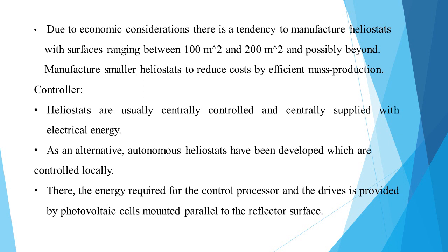Controller. Heliostats are usually centrally controlled and centrally supplied with electrical energy. As an alternative, autonomous heliostats have been developed which are controlled locally. There, the energy required for the control processor and the drive is provided by photovoltaic cells mounted parallel to the reflector surface.